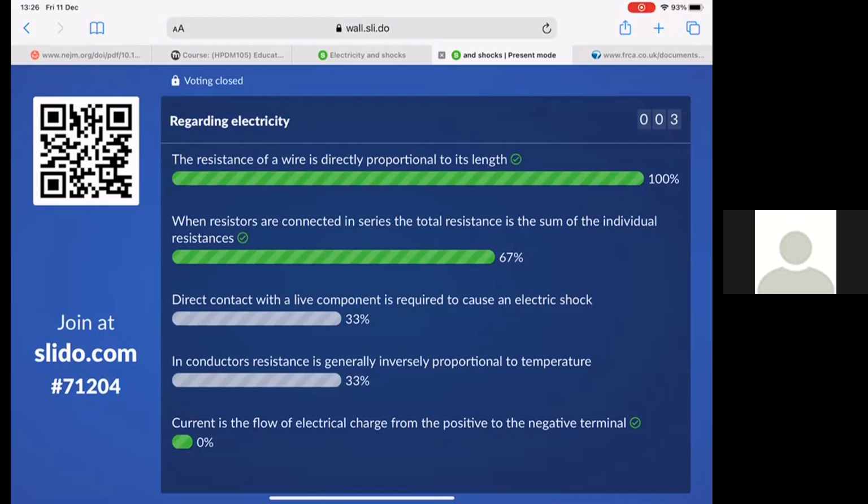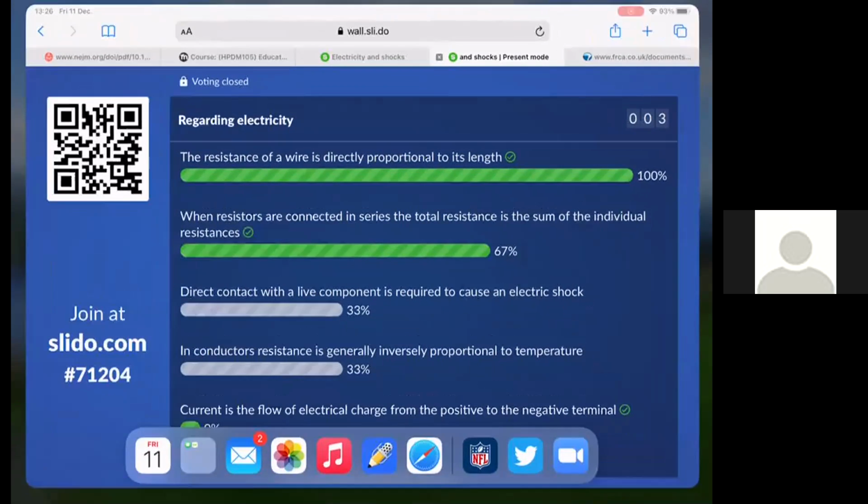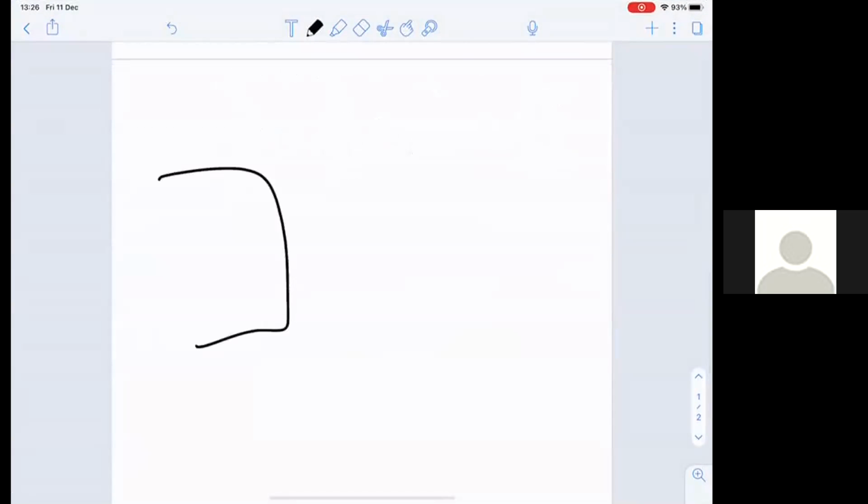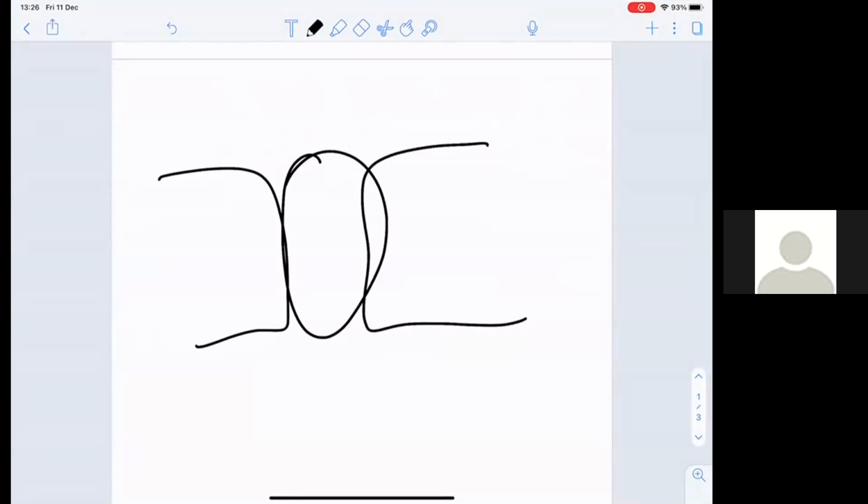So it only works with alternating current. And this is because we come back to the basic physics concept that any moving current induces a magnetic field, and any moving magnetic field induces a current. Right? So if you have an alternating current, because it's moving back and forth, you start to create a magnetic field around it. And that shifting magnetic field, if you hold another wire in it, will induce a charge in the other wire. And that's how you have floating currents. That's how current flows without direct contact from this one to this one.